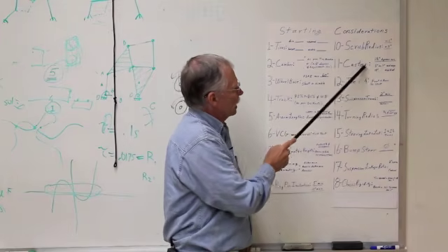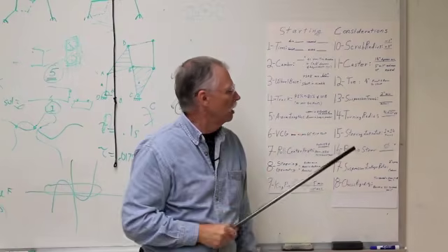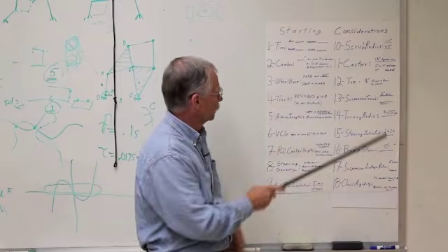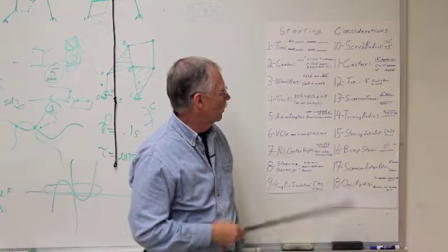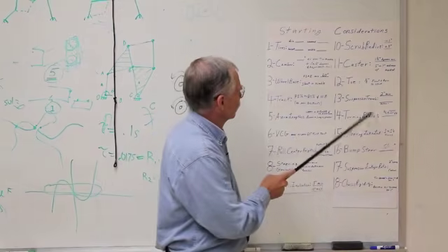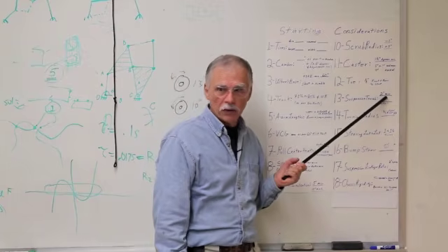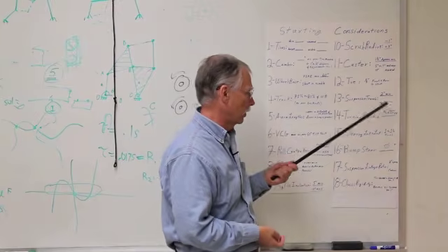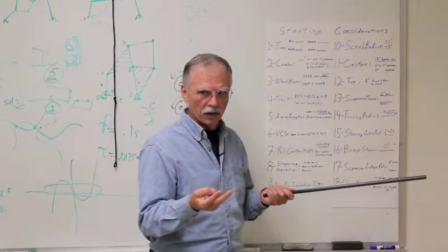5 to 7 degrees of caster would be what I'd consider mid-range, and up to 15 degrees would be toward the high end of a caster setting. Okay, toe, simple, 1/8 inch, front and rear wheels to start. Adjust from there. Suspension travel. In FSAE, you're required by the rule book to have 2 inches minimum. Okay, so you got to have 2 inches, your actual suspension travel to be determined.